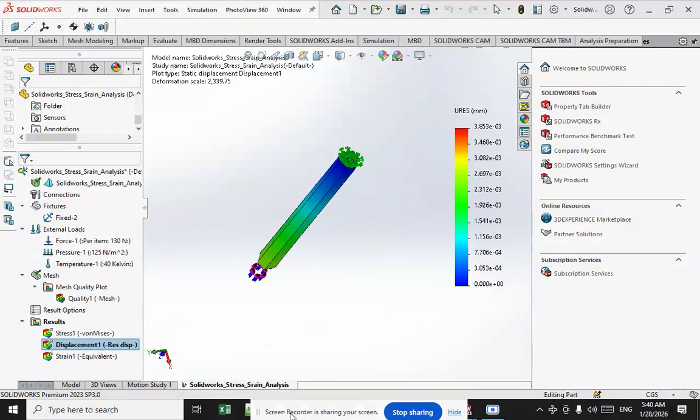In simple terms, we can define stress as the force of resistance per unit area offered by a body against deformation. Stress is the ratio of force over area, where S is equal to R divided by A, where S is the stress, R is the internal resisting force, and A is the cross-sectional area. Strain is the ratio of change in length to the original length when a given body is subjected to some external force, which is equal to change in length divided by the original length.